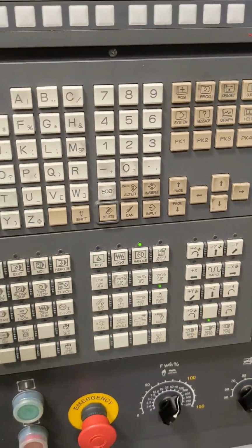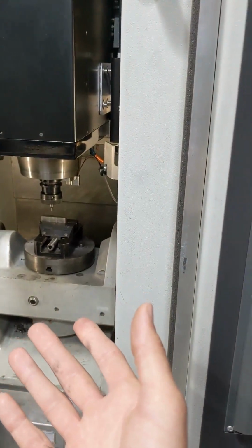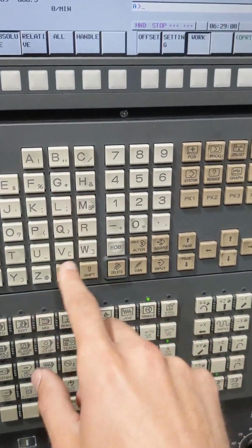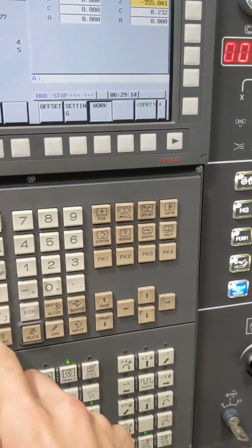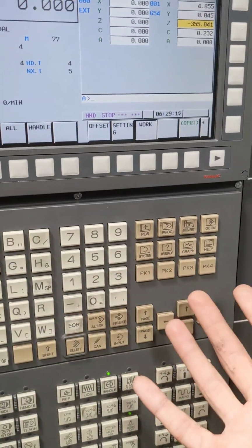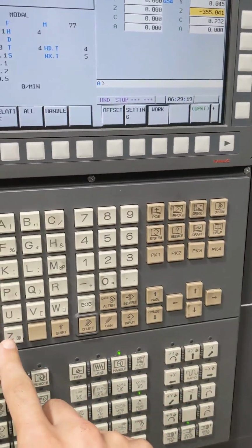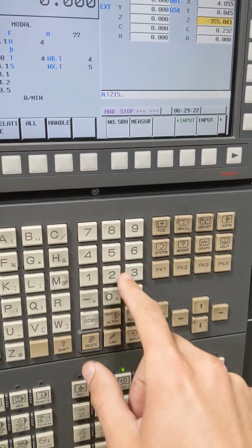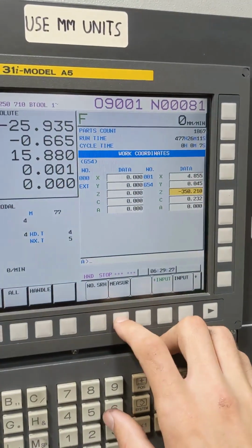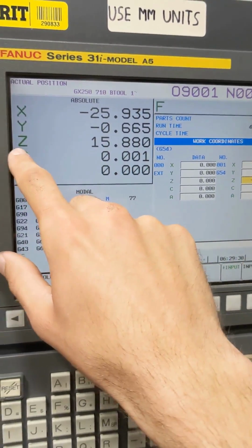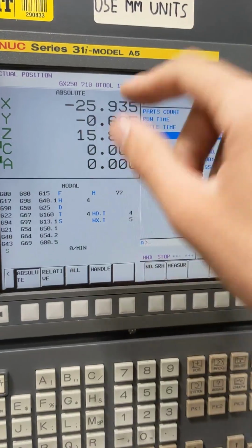The way I like to do this is you just tell the machine where your Z height is. So we just found our G0 location, but we also added that length of the dowel pin, that 5/8 inch. So we tell the machine that 5/8 is 15.88 millimeters. So we're going to go Z 15.88 millimeters and then measure. You'll notice that our Z height changed to 15.88.